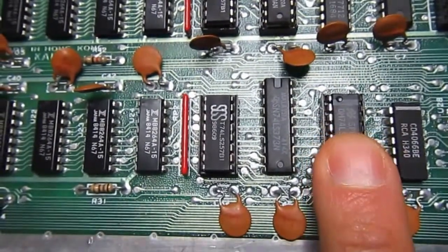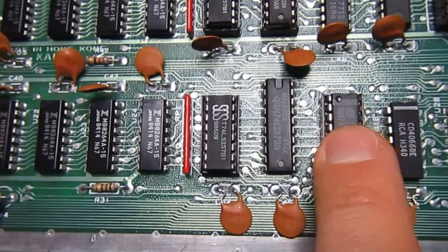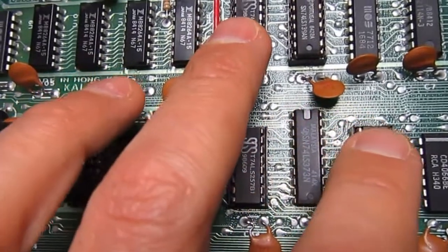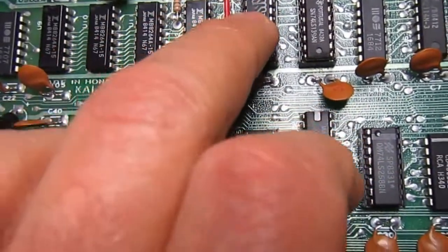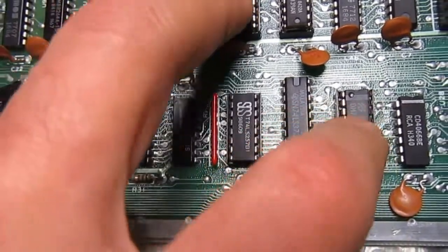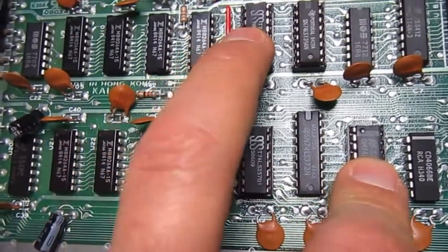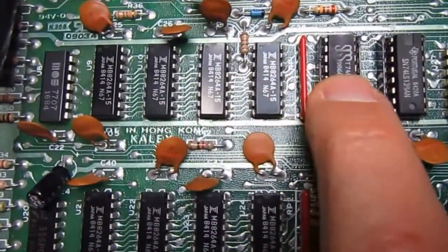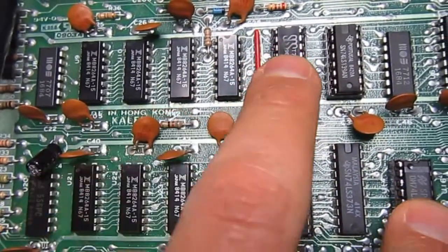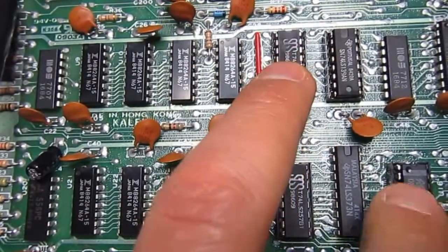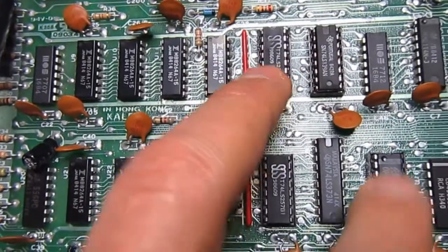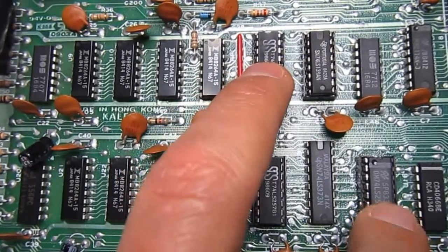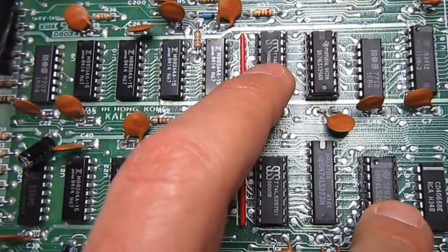So first I changed U14, then I checked the diagram, and I discovered that U13 and U14 were driving the same address line at the same time, so I had to change also U13, because two chips that drive the same line fail, probably both. And actually I checked, they removed the chips on another C64 board and they were shot anyway.